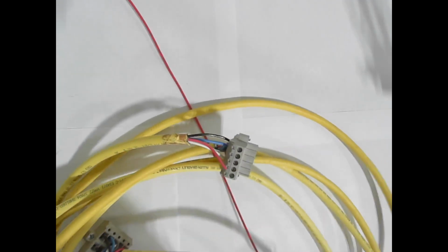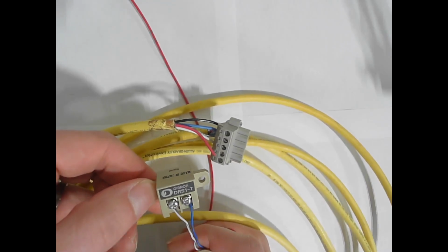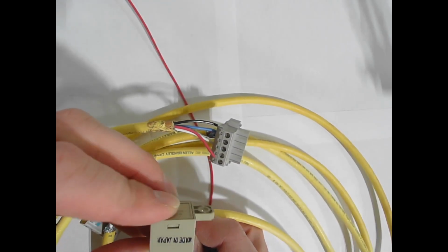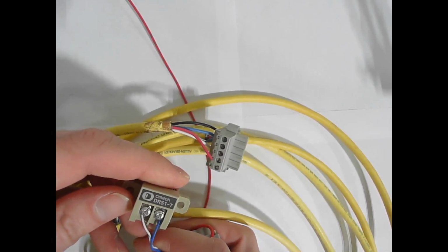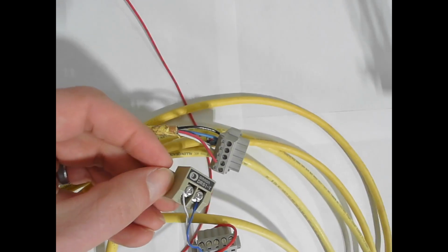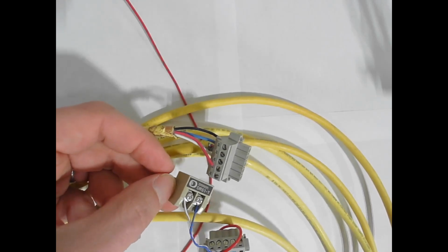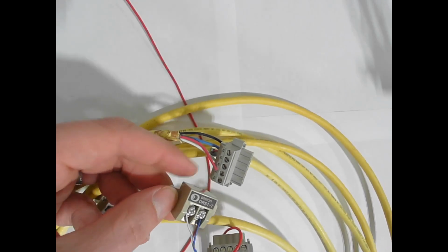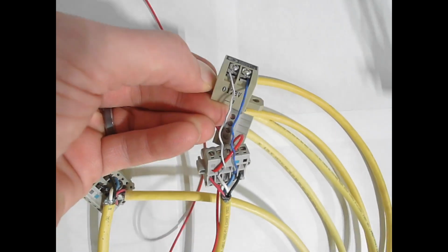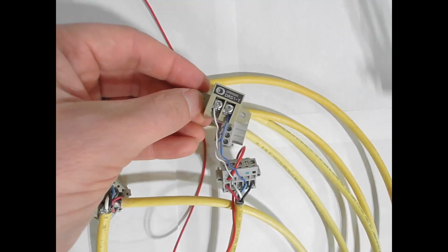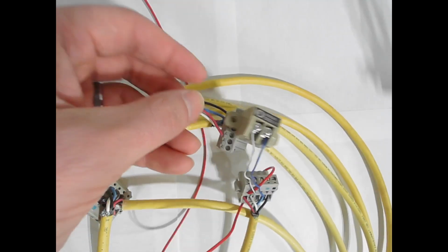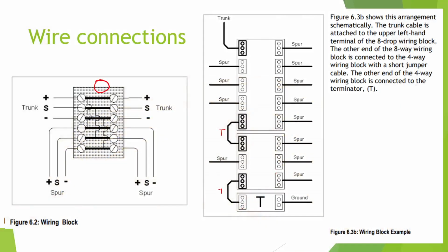Well, here would be an industrial terminating resistor. This one was made in Japan, but that is all this is. I don't know what the value is, but that would be a possible terminating resistor there. This is why I say you don't want to just go grab your little quarter watt resistor and shove it in. Technically, it would work. This is much more, I'm going to call it industrial, right? It's got little screw terminals on it. You've got a place to put the wires into it. Everything's a bit better with this type of thing. Is it going to cost you an arm and a leg? You damn well better believe it. But it's probably going to be a better answer for your industrial application.